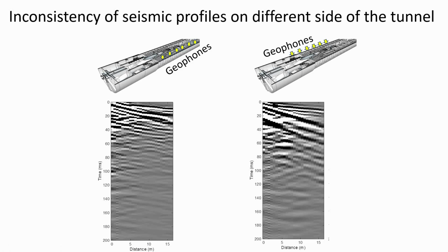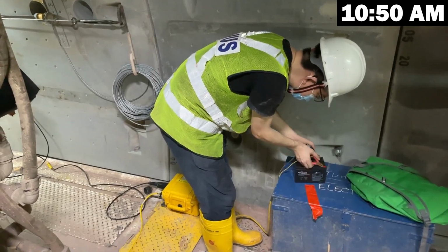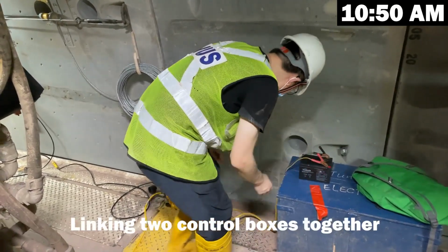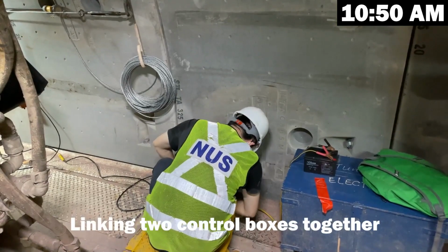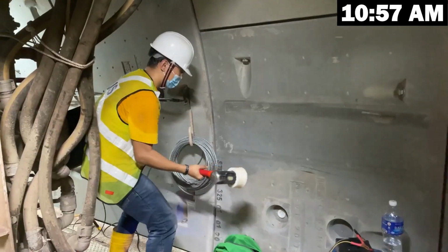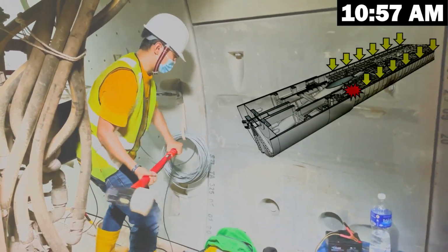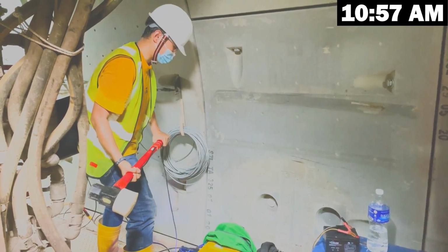To get more reliable data and reduce the influence of the surrounding layer on one side of the tunnel, we need to do a two-sided observation. We repeat the whole deploying process on the other side of the tunnel and link the two control boxes together to get vibration data from both sides. To get a higher signal-to-noise ratio of the data, we need multiple shot activations and stack the data together.